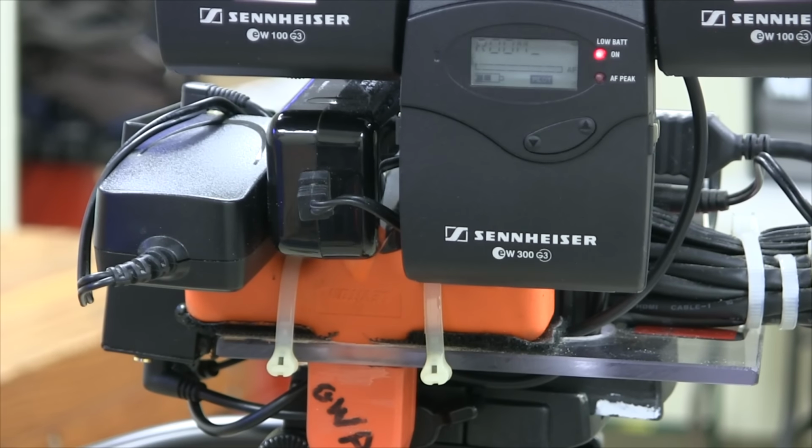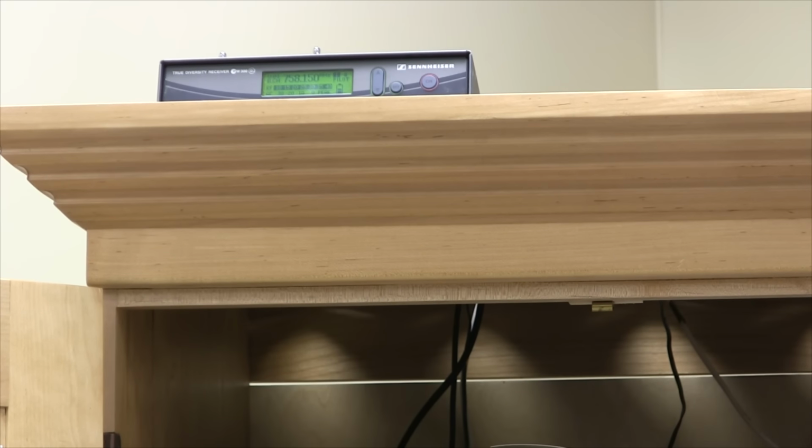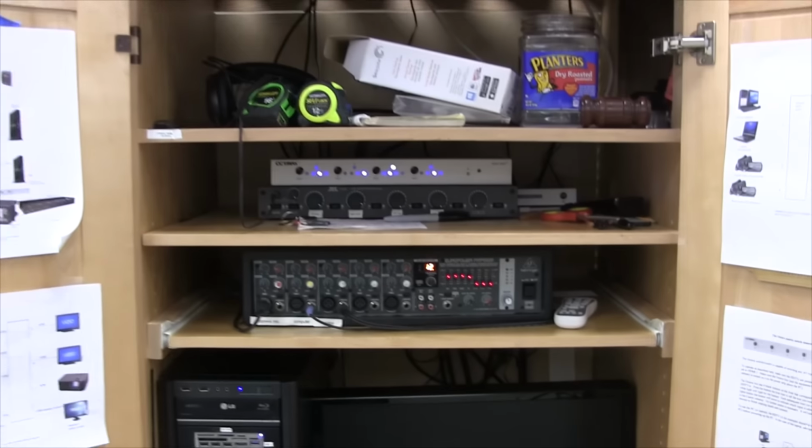A recently added device to the camera platform is the wireless audio transmitter. After considerable study, we determined that the latency of transferring audio through the wireless HDMI was causing considerable echo in the classroom. The delay of the audio through the wireless system was in excess of 100 milliseconds due to the encryption and decryption that was going on inside due to the HDMI standards. We solved it by putting the audio through the wireless system intended for stage use that would have no discernible latency.